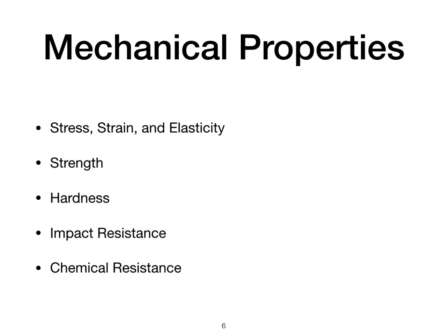Hardness. Hardness is the ability of a material to resist being scratched, fractured, or permanently deformed by the sharp edges of another material. In other words, it is a measure of a material's resistance to abrasion. You can measure the hardness of glass by using indentation tests like Brinell hardness, Vickers hardness, Rockwell hardness, and some of the scratch tests like the Mohs scale.